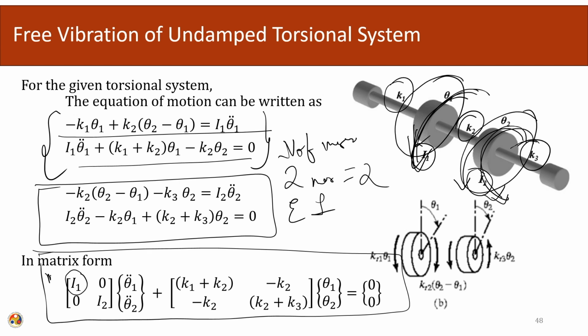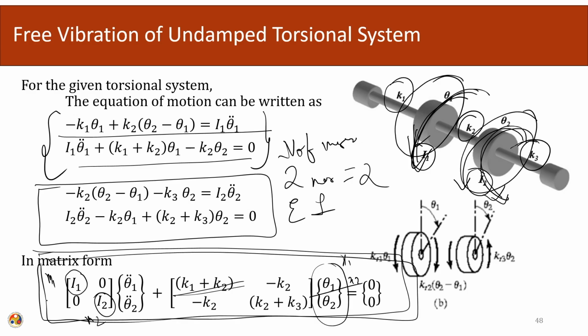Okay. So, instead of M1, M2 now we are using I1 and I2. Okay. And earlier we had translational motions x1 and x2. So, now we have rotational movements and the rotational stiffness. Okay. But the formulation is same, again this is a 2 degree of freedom system, the motion is in the rotational form instead of being in the translational form. Now, it has changed back into the rotational forms.